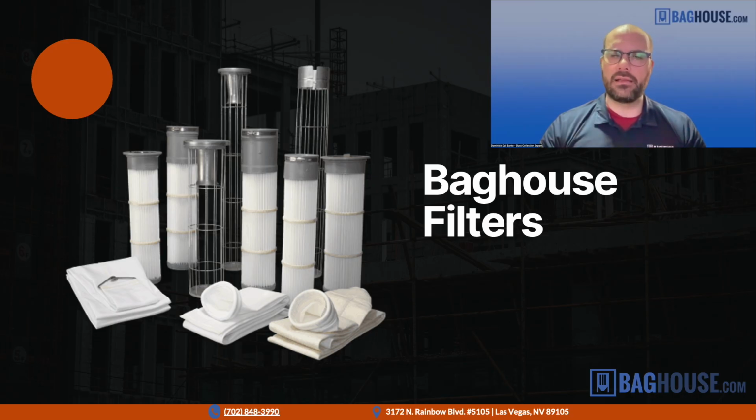So the polyester bags are good up to about 265 degrees Fahrenheit. As long as we're under that temperature, we're pretty much going to use polyester bags exclusively because they're the cheapest, the most robust, and the most widely used, and least reactive. If the temperature exceeds that, then we're probably going to go to aramid next, which also is very robust.